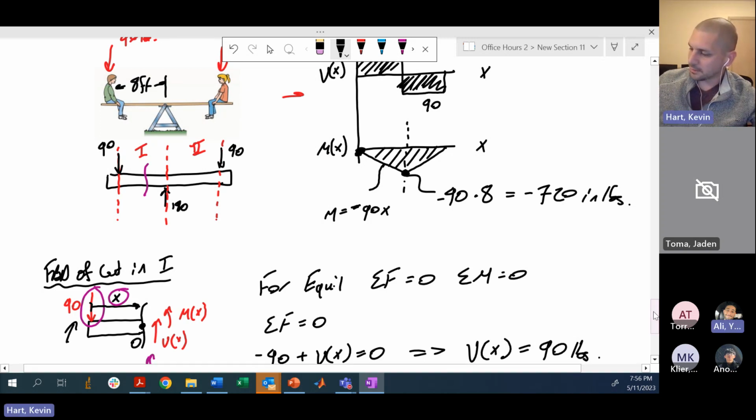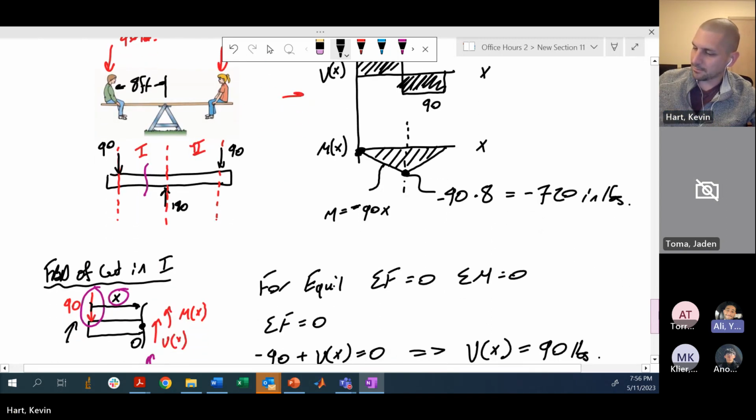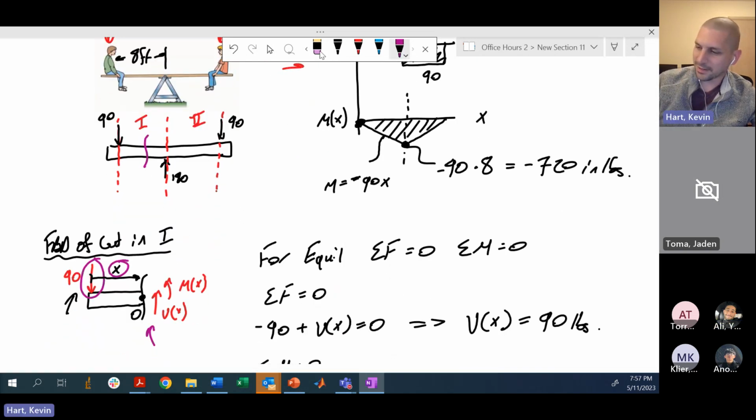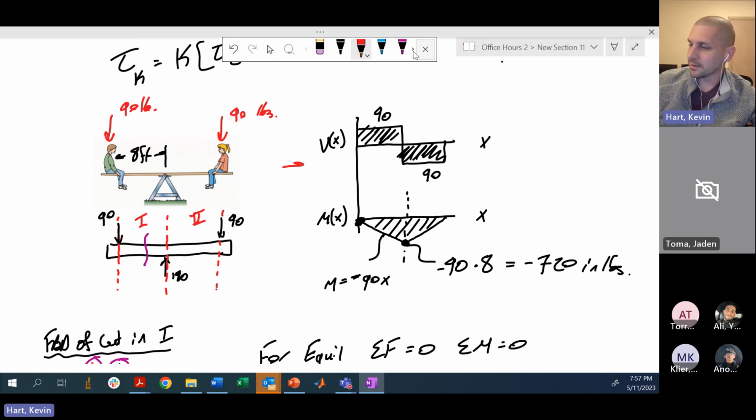Professor, that's all based on your shear force diagram, can't you use the shear force as the slope of the moment? So wouldn't it be 90x, like positive, the way that you had it? Yeah, so by convention, typically you would draw this shear downwards. And in that case, you could do that. So if you draw shear downwards, which is sort of the conventional way, your diagram flips.